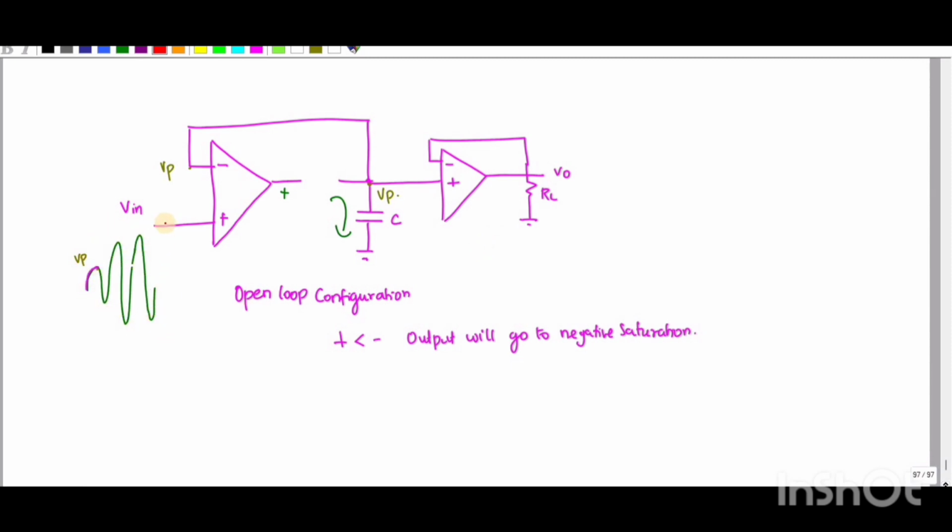So basically, if instead of the normal diode I use a Schottky diode, it has a quick response time, so it will quickly detect the change in the input signal.